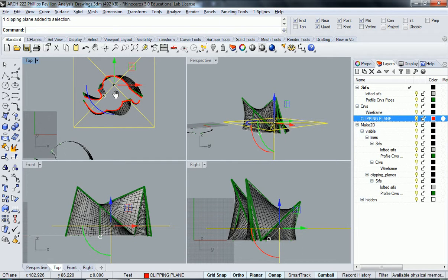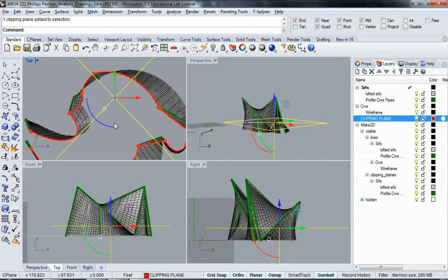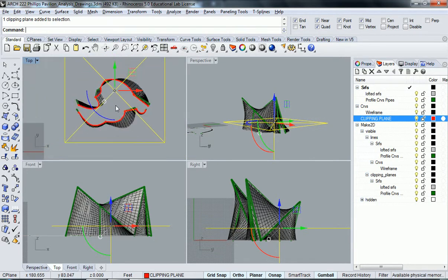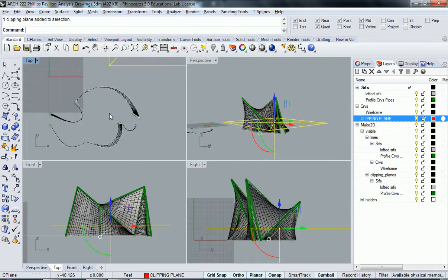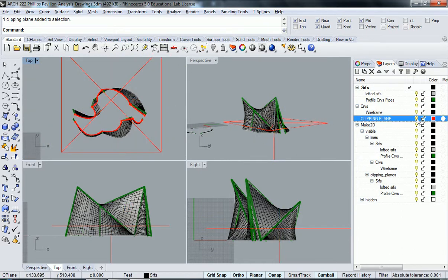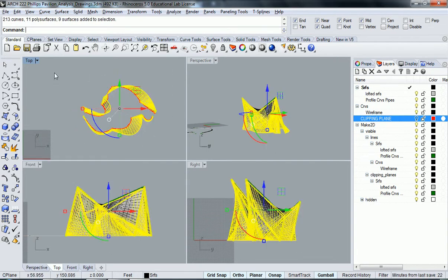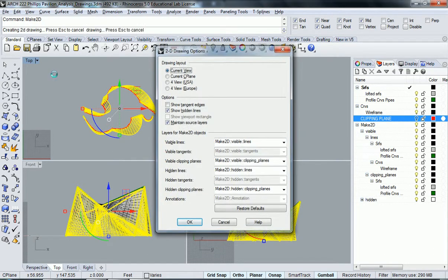First it was 4, and then I moved it up 6, so that way it could be a total of 10. And so I think there's enough variation here to where I can make 2D again on this one. So I have officially moved it up 10 feet from its original. I'm going to select everything in top view, and I'm going to make 2D again and hit OK.